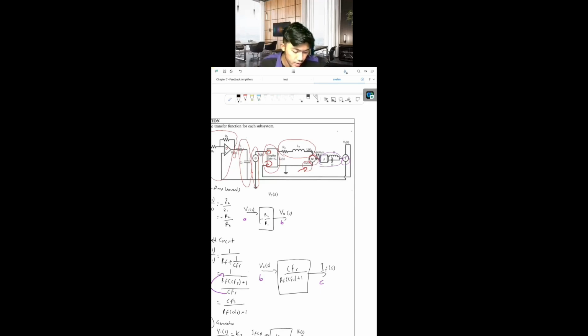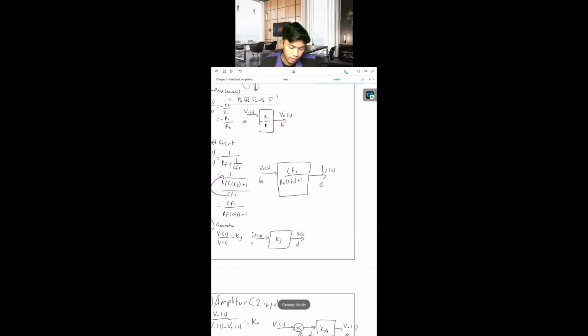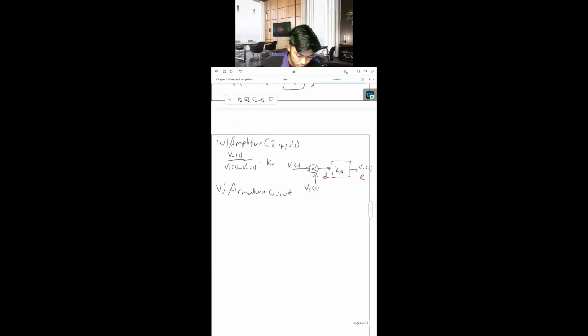We know that the V back is the feedback of our subsystem here. So we write down the circuit I_A(s) over V_A(s) minus V_back(s), we get 1 over R_A plus L_A s in the s domain.